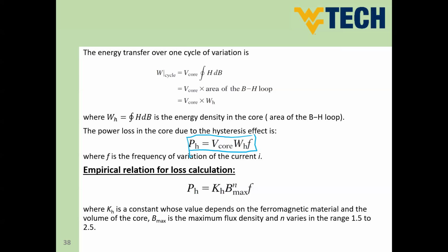For that, in electrical machines, for instance, we have some drive systems. You will learn that by the end of this class, by the end of the semester. We have something called variable frequency drives. Variable frequency drives try to reduce the harmonics and the high order frequency waveforms in order to reduce the hysteresis loss in the machine. We expect that if you have an AC motor supplied by an inverter, the main frequency is going to be 60 hertz, but you will have some subharmonics and harmonics. The harmonics can go up to several kilohertz.